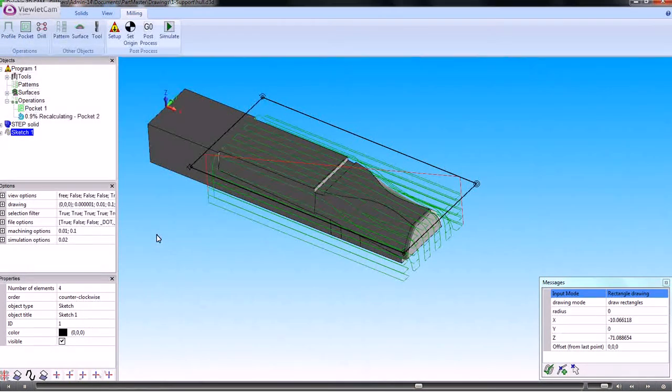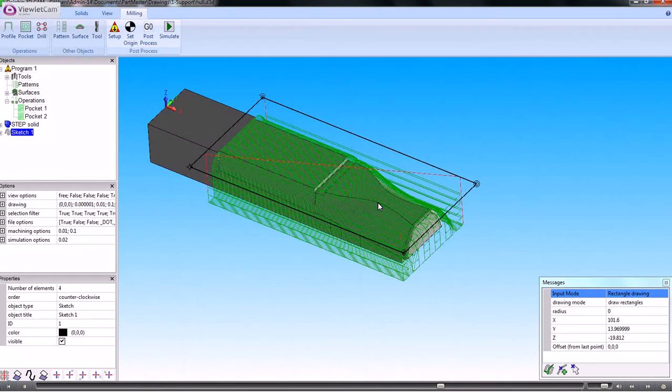So that's now recalculating that surface, but this is a finishing toolpath, so the calculation time will be a wee bit longer. And the other thing that we could do here to speed up the processing would be to make a smaller rectangle for cutting so that it's only considering just this one area here. Okay, so that's created the toolpath.